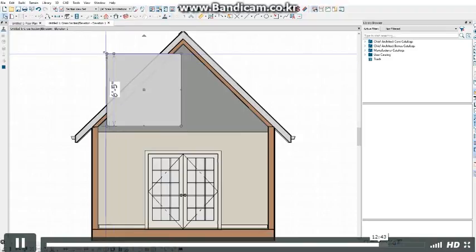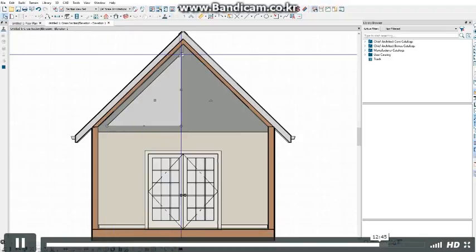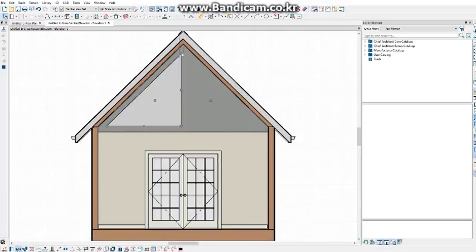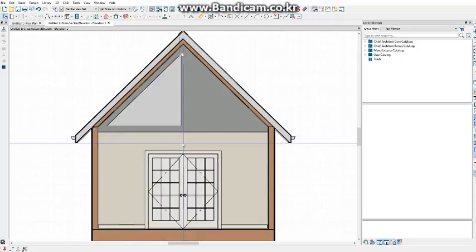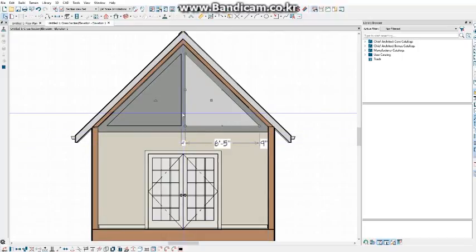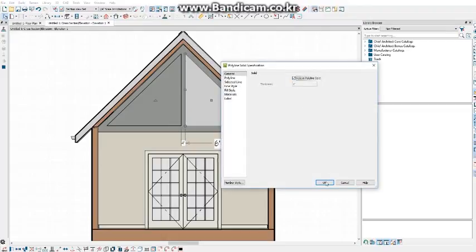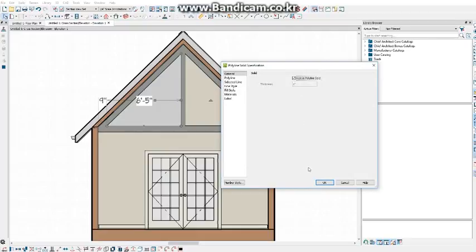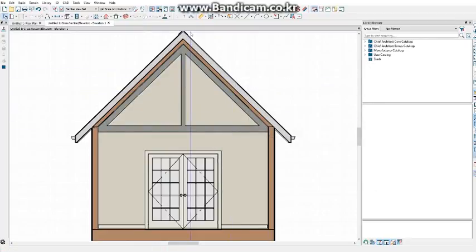and then shape it so that it's completely contained within the original. Then I'm going to copy this one by using my copy paste tool and reflect about, hover over the wall and click. Then I'll open up each one of these two and make a hole in the original polyline solid. Then I'll create another piece with another polyline solid.